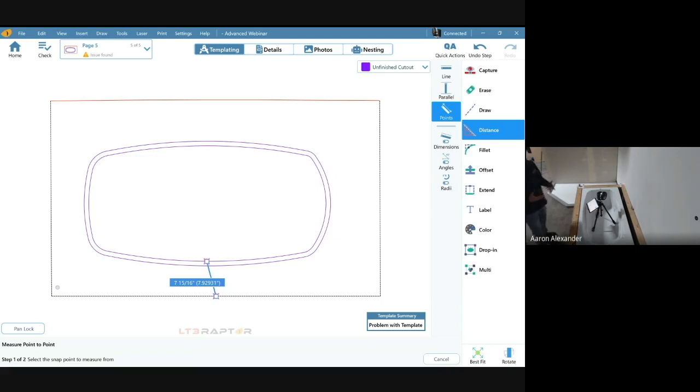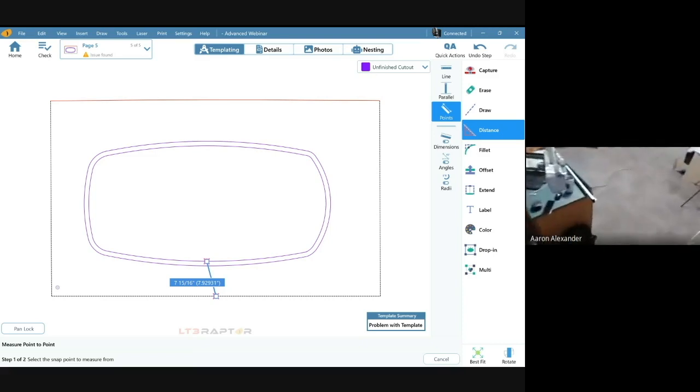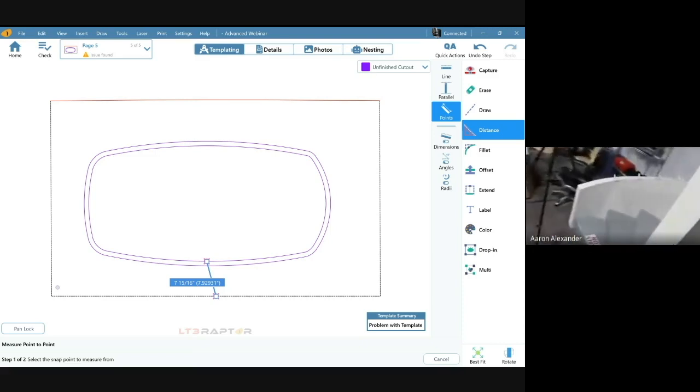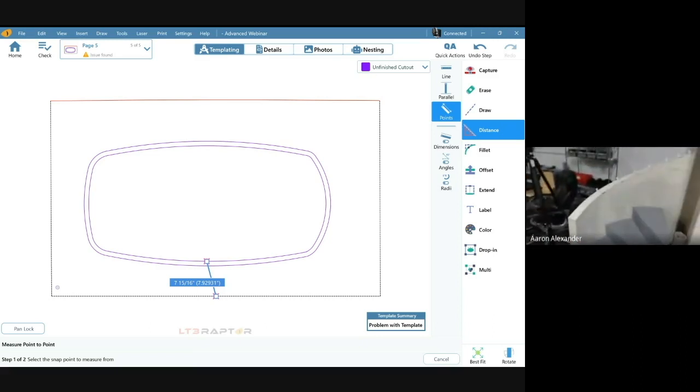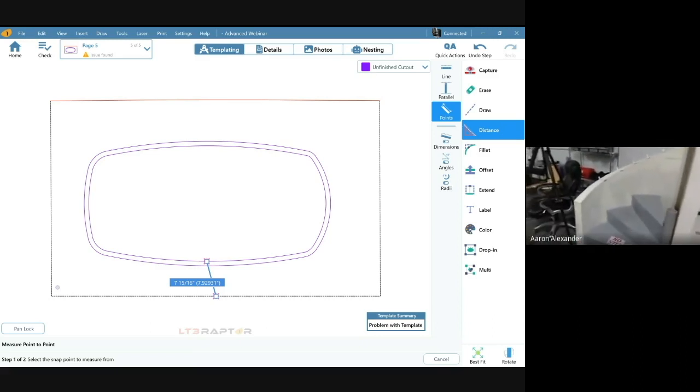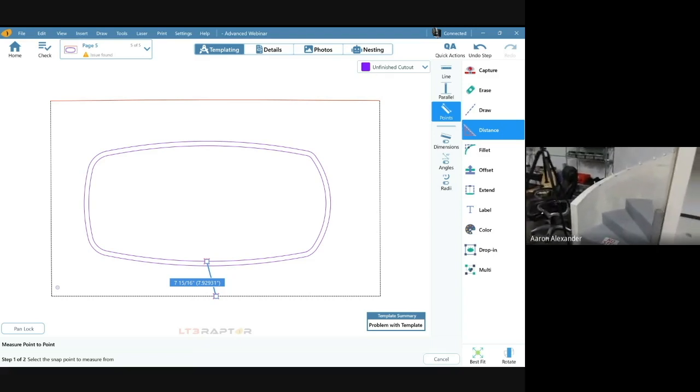Now, we can also scribe drywall in arc mode. So you could do continual arcs. The only thing I really have radiused here is this wall here. So if you were, for example, going to put a countertop in here, you know, it's a doctor's office, dentist's office, a radius reception desk kind of deal, you could be in arc mode and you could start here in continuous arc mode and you could scribe in arc mode. So it's 1, 2, 3 gives us our first arc, those 3 points.